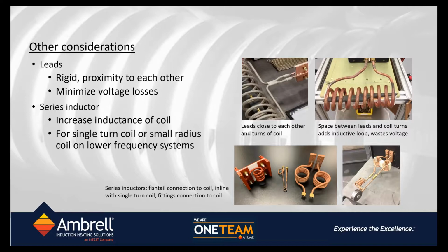In some cases, you actually want to incorporate the loss in the induction heating coil feeds. Those are shown on the bottom part of the picture of your slide. We actually have sacrificial coils sometimes to match the inductance so as to resonate the coil on the induction heating power supply.